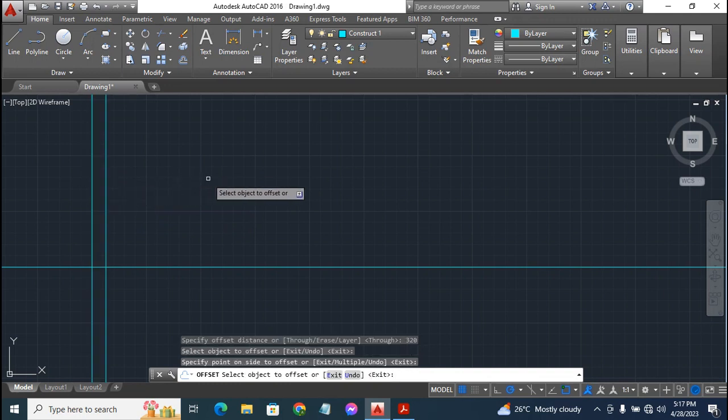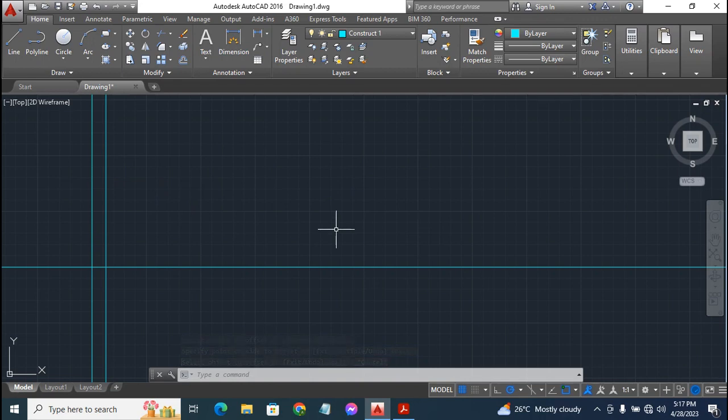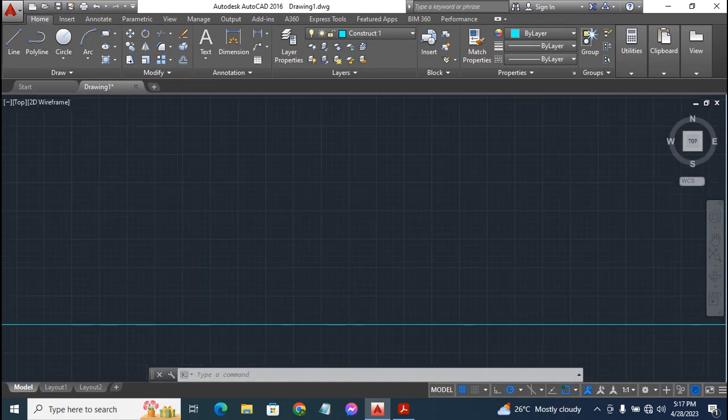That is it. You see that the offset distance is kind of small, so we have to zoom out so I can see what I'm doing there. You can use the roller part of the roller ball on your mouse to do that. You roll it upwards in order to zoom out. You see it's kind of getting out of the center, so we have to pan to centralize our drawing. So you click on pan by the right of your screen there.